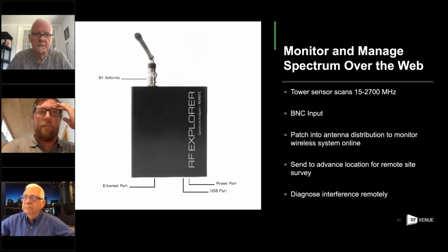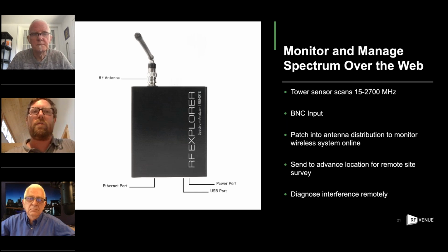It depends on the span for sure, which is why we typically recommend that people pick at most, what, Don, 600-700 megahertz span before it starts to slow down a little bit, which should cover you from at least portions of VHF up into 900. And then you can drill in from there, right? Yeah. It's probably easier to pick presets if you need to use a bunch of ones than to wait for it all to scan, but you can do it either way.